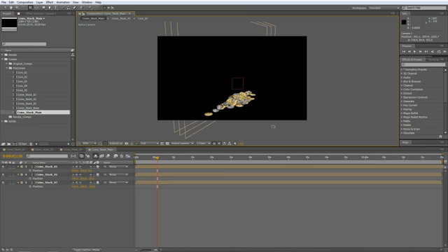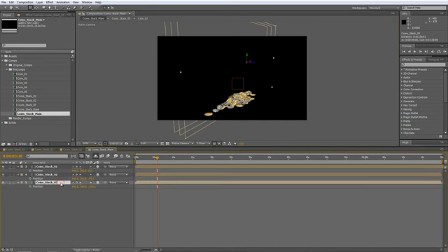Of course, if you want it to be a perfect stack, you can duplicate these 2 and place them behind the first one, or rather create 2 more layers and repeat the same process we just did, just to make it more random. Now all you need to do is place this composition in your After Effects 3D scene and collapse its transformation, place a camera, and there you go, you get yourself a 3D coin stack. And all within After Effects, rendered, powered by the power of Newton.